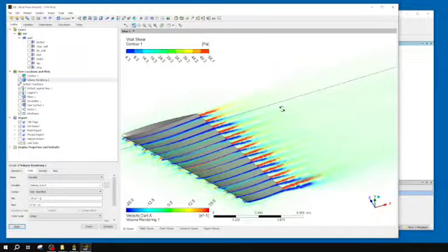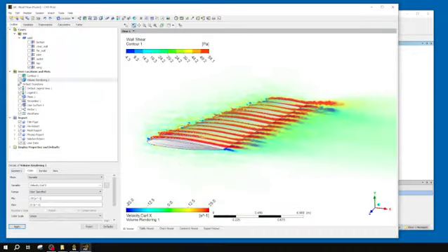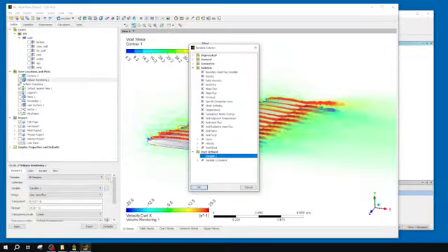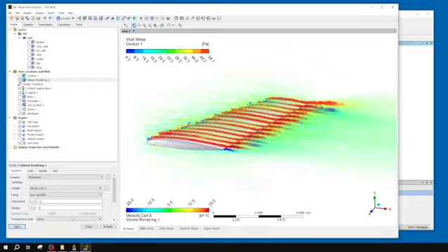You might be wondering right now why I didn't use just velocity curl to begin with, and I very well could, and I'll show you what that might look like. If I used velocity curl x to start with, still using my 0 to 25 bounds, and I apply that, what you'll see is that all my bottom surface is going to disappear. I'm going to have no blues show. Giving it a little time to calculate that.